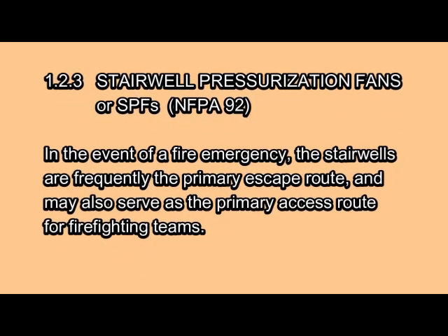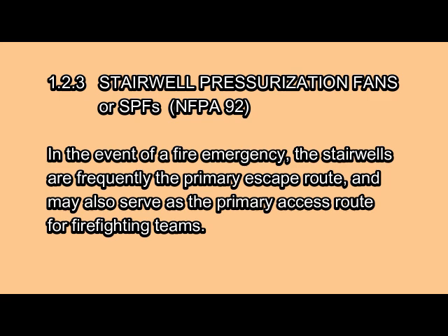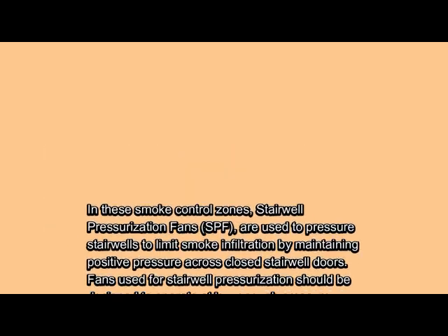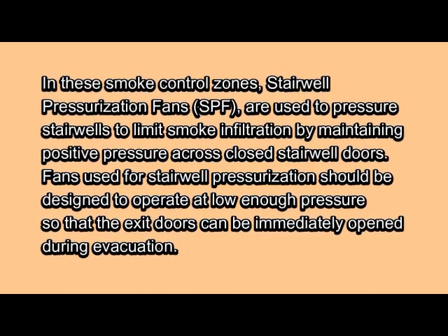1.2.3 Stairwell Pressurization Fans, or SPFs, and NFPA 92. In the event of a fire emergency, the stairwells are frequently the primary escape route and may also serve as the primary access route for firefighting teams. In these smoke control zones, stairwell pressurization fans, SPF, are used to pressurize stairwells to limit smoke infiltration by maintaining positive pressure across closed stairwell doors.